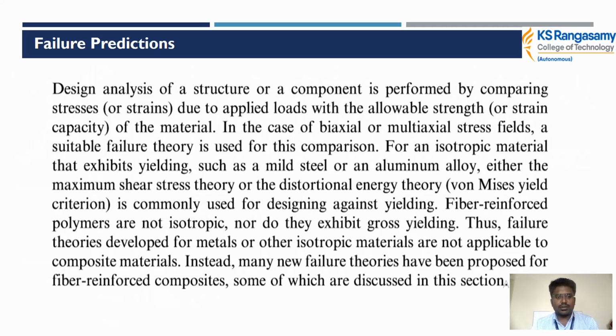Either the maximum shear stress theory or the distortional energy theory is commonly used for designing against yielding. Fiber reinforced polymers are not isotropic, nor do they exhibit a clear yield point. So the failure theories developed for metals or other isotropic materials are not applicable to composite materials.